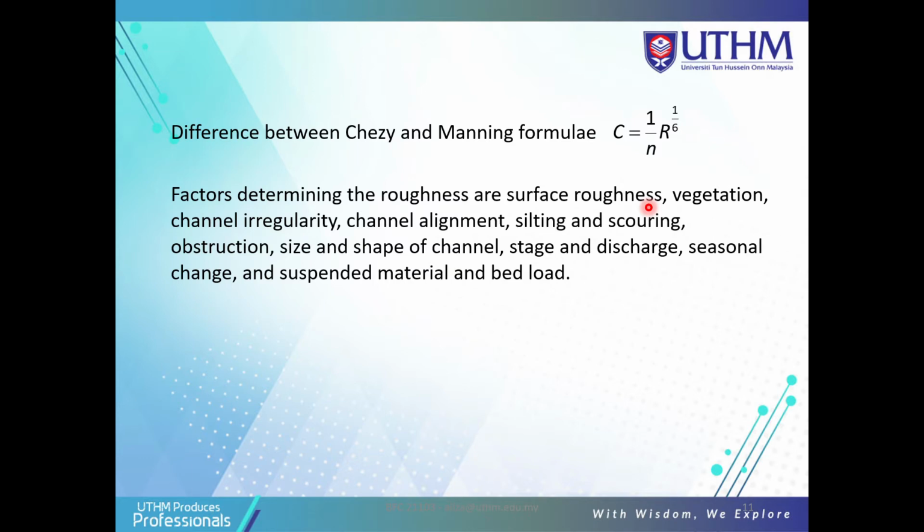The factors determining the roughness are surface roughness, vegetation, channel irregularity, channel alignment, silting and scouring, obstruction, size and shape of channel, stage and discharge, seasonal change, and suspended material and bed load. So all these factors will determine the roughness.